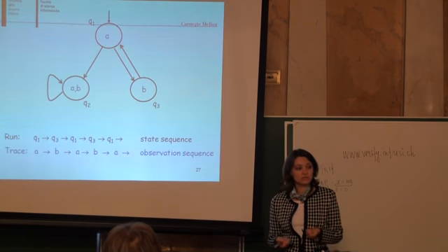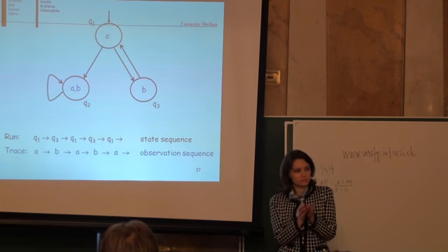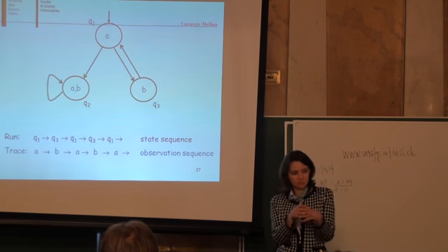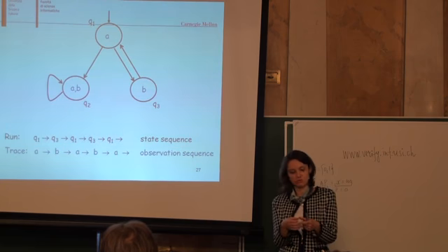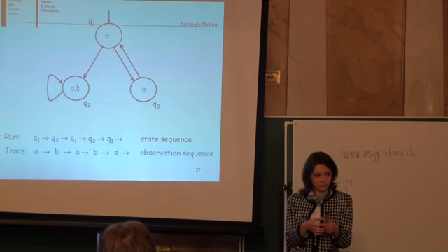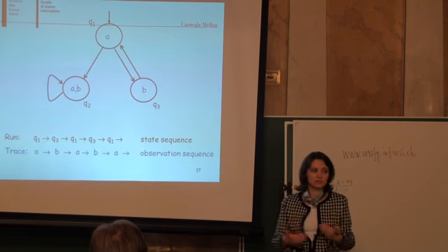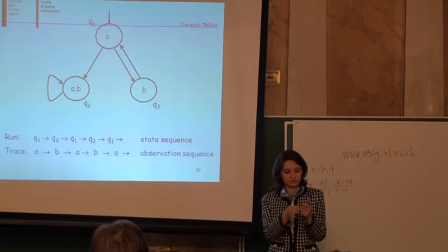So what I'm doing, I'm simply having a product. I have a Verilog program describing how this chip executes its own functionality. So I'm simply encoding all possible traces for the Verilog program and taking a union of all of these traces. I'm defining a language of my chip.